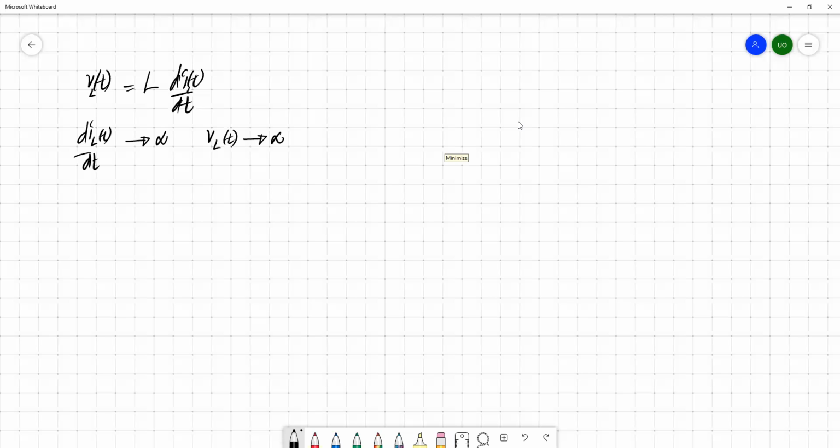Function of the capacitor, the voltage. Yeah, we can simply say that one of the functions of the capacitor is smoothing the voltage, because it can buffer the voltage, or act as a sink for this kind of variation. That's why we use capacitors as smoothers in rectifier circuits.